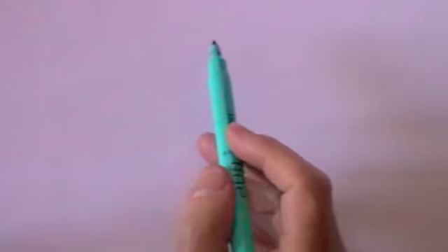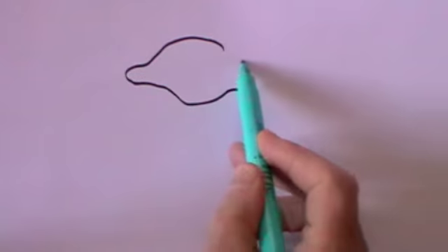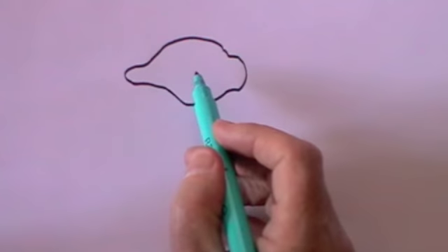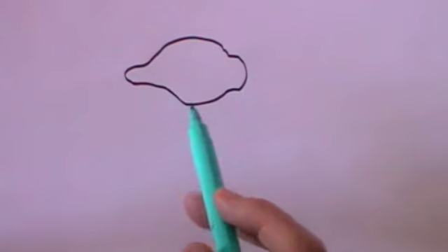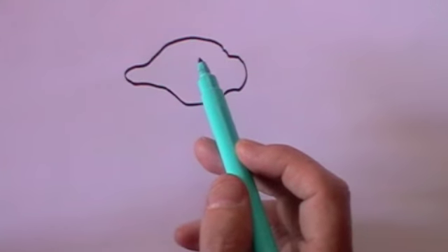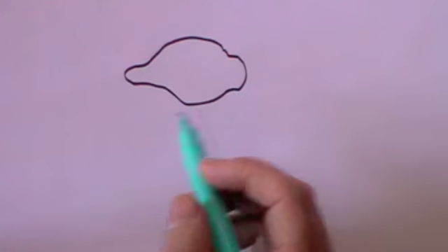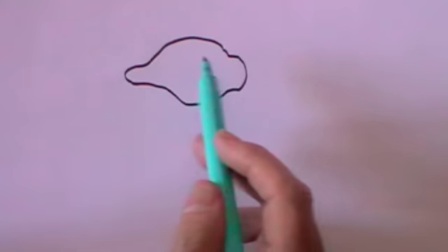How do you find the centre of mass of a two-dimensional object? With three dimensions it's slightly more difficult, but I can show you how to find the centre of mass of a two-dimensional object this way. What you do is you take the object and you stick a pin through it into the wall. So you pivot it somewhere, anywhere, it doesn't matter where you pick, somewhere here.